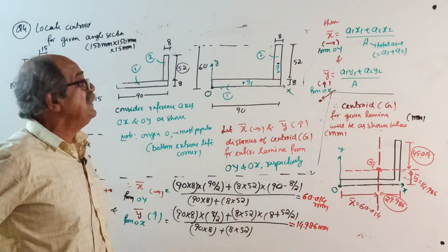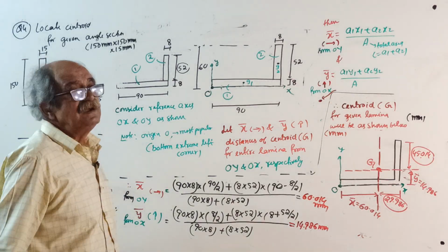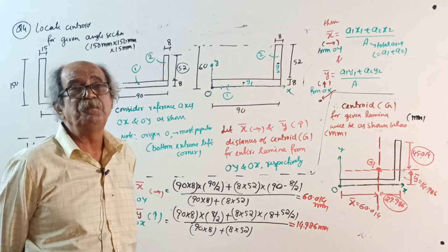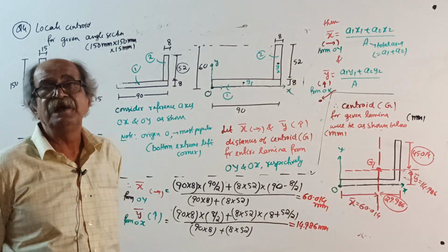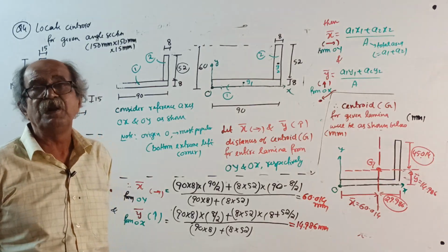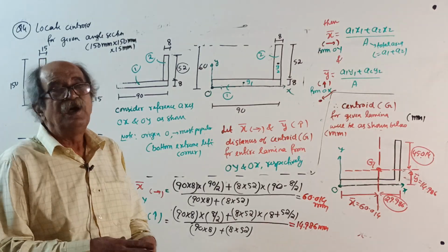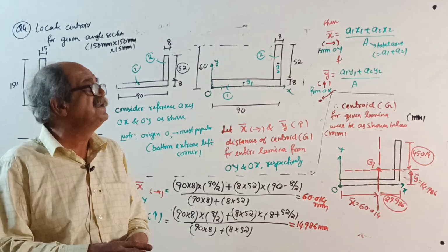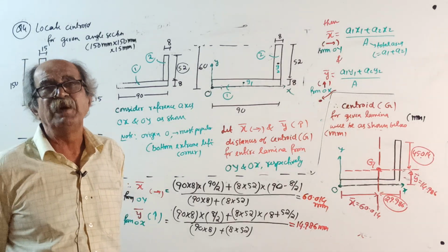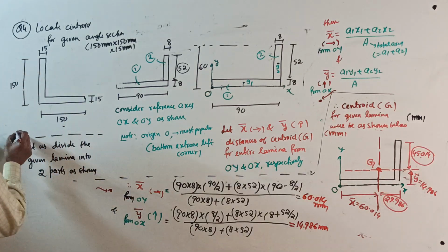See, orientation can be anything. I will put this way orientation. Okay. Now, why am I telling? Because this is a very popular angle used in steel structures, especially plate girders. Nowadays, bolted plate girders are not used. In olden days, bolted or riveted plate girders were widely used. You require huge flange angle. So, long back, when I took steel structures class, design and drawing of steel, I usually selected ISA 150 by 150 by 15.